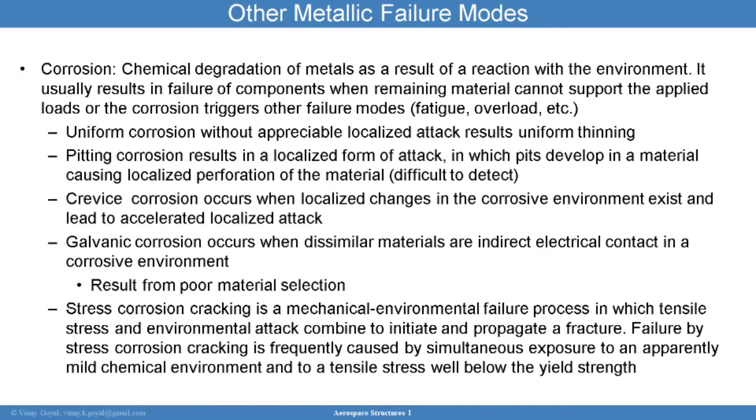And the way that can happen is that because corrosion has degraded a portion of the material, the remaining part of the material that has not been affected by corrosion will then have to take the additional load that the corroded material could not take. That shift and redistribution in load then decreases the capability of the undamaged material through fatigue or overload.